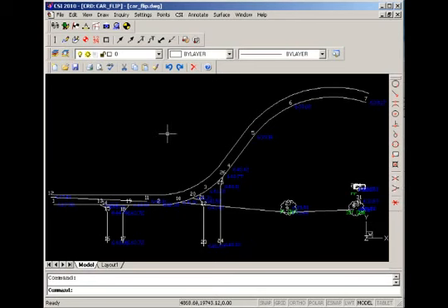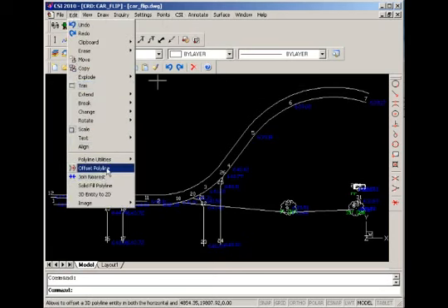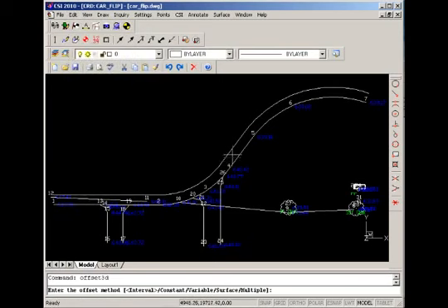Next, we're going to create some of the terrain model. We're going to start by completing the road profile here. So let's go and offset polyline. We're going to make a 12-foot lane based off the center line of the road. And we can give that a percent slope from the crown to the edge of pavement of about -2%. And we pick our polyline, and we're going to offset it over here to the north side.